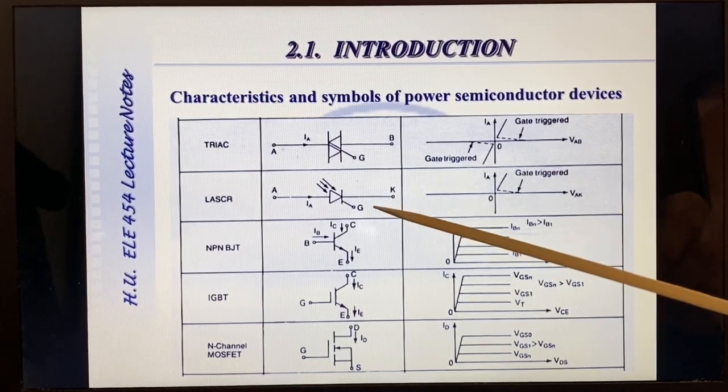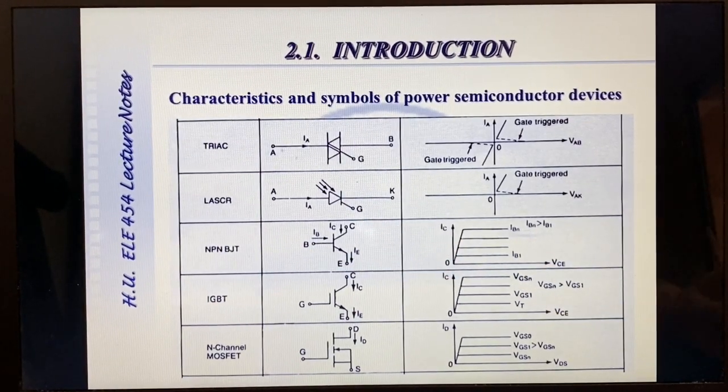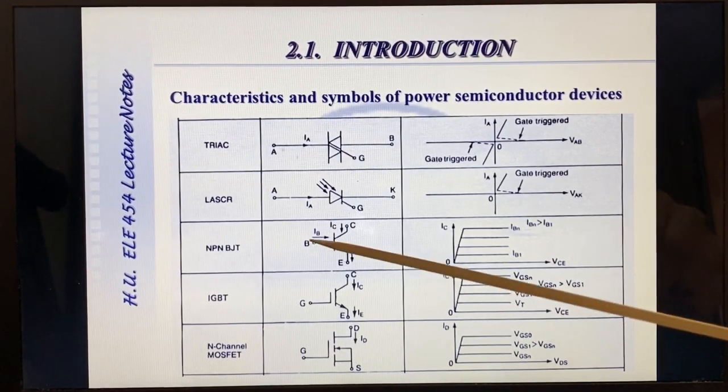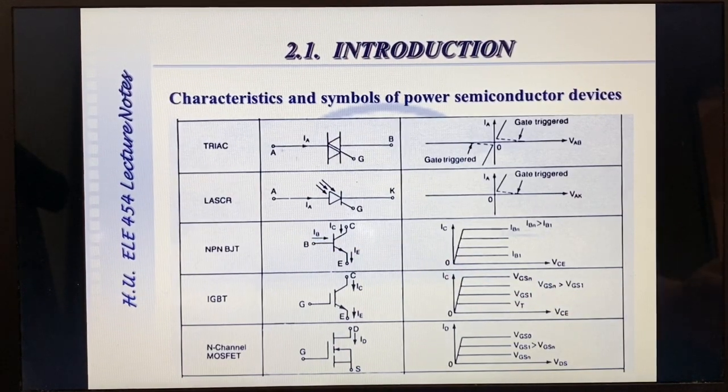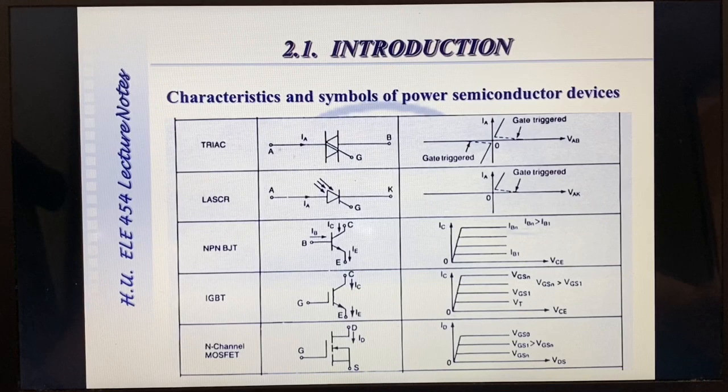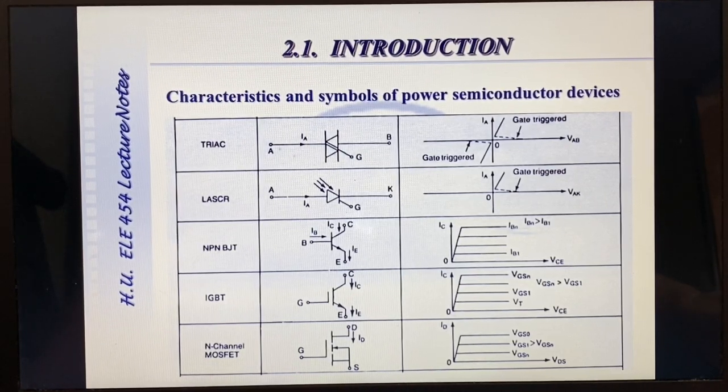It has again a collector, emitter and base terminal, and it is put into conduction by applying a base current. Usually Darlington pairs are used here in a chip, more than one transistors cascaded, so as to obtain high current ratings at the output.